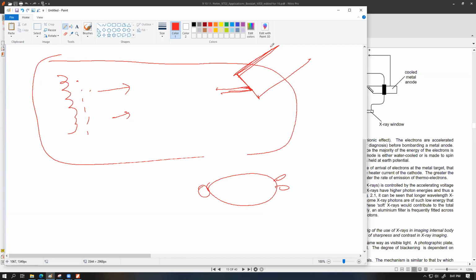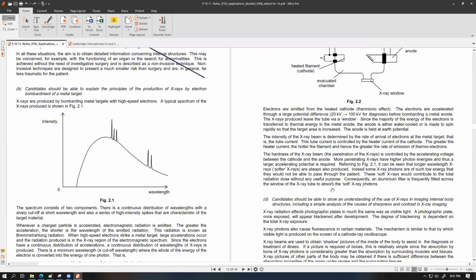So what we can do is continuously rotate this target so that this beam of incoming electrons will not always hit in the same location. We can distribute that hitting location over a larger circular or cylindrical region so that the heat is distributed and it is easier to dissipate that heat energy. So that's also a very required operation for the device to be long lasting. That's pretty much what is said over here for a pretty big part.